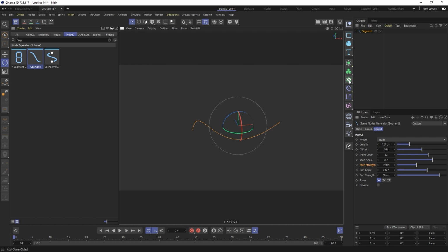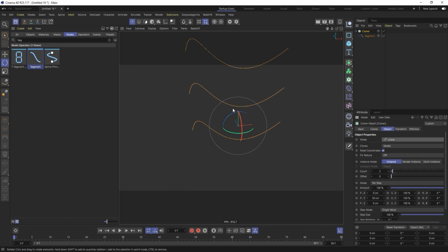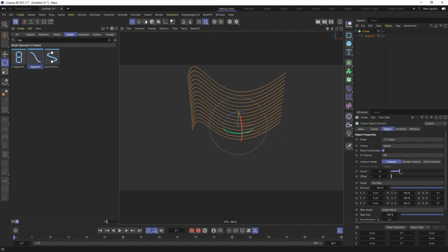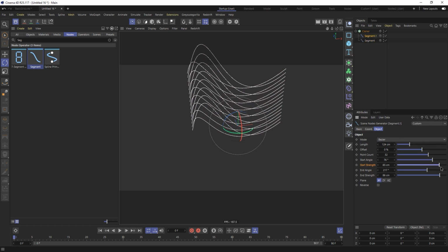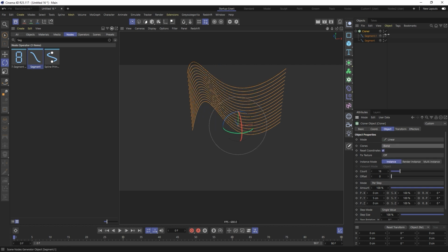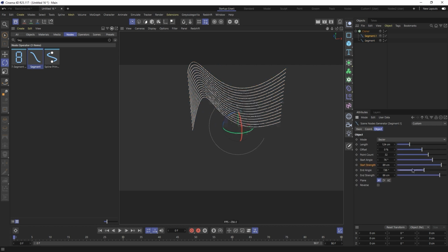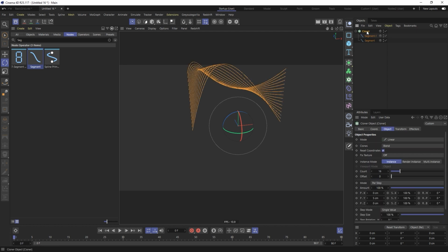In fact, let me show you. If I put that into a cloner and set the cloner to linear, we should get a series of them cloning as they move upwards. I'll just separate them a little bit. So I had a bunch of copies. I can now add 2 of them and put different settings in them, and as long as I set the cloner properly to blend, then we are blending between these 2 different shapes and however we want to lay them out. So having this line be parametric does open up a lot of opportunities for very controllable rigs.